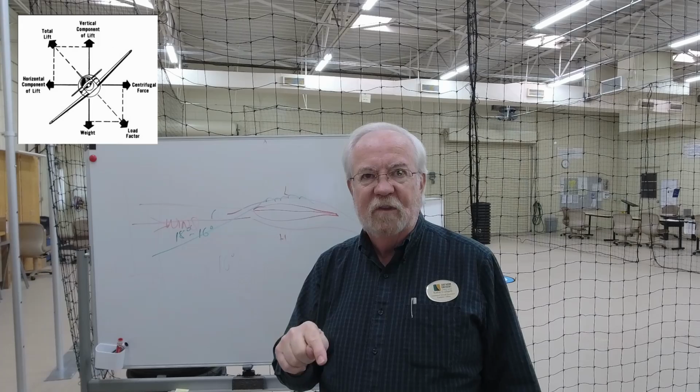And they will get more specific on those charts. But the basic question is, which flight maneuver increases the load factor? Of course, B, turns. Another related question is, when operating an unmanned aircraft, the remote pilot in command should consider that the load factor on the wings or rotors may be increased anytime the aircraft is subjected to a maneuver other than straight and level. So straight and level, that's the key thing. Straight and level produces no increase in load factor. Turns, sharp climbs or descents produce some kind of load factor.